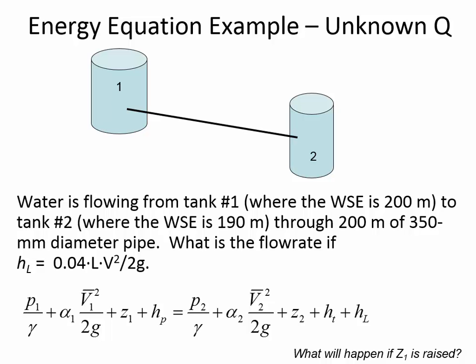You're right. So the phrase I want to introduce is driving force. Why was the flow going from 1 towards 2? It's because there was more elevation at 1, meaning it flows from high energy towards low energy. Flow always does that, whether it's just an isolated pipe section that we're thinking about.